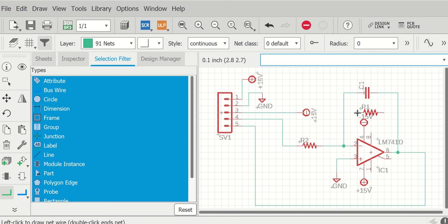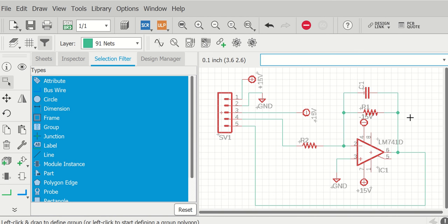Now it might look right, your design, but you might get some errors. And I don't know if you remember, but yesterday we talked about how we can check the errors in the schematic. So instead of doing it at the end, once you make your schematic, you can check if there is any error. And that's just by typing ERC.